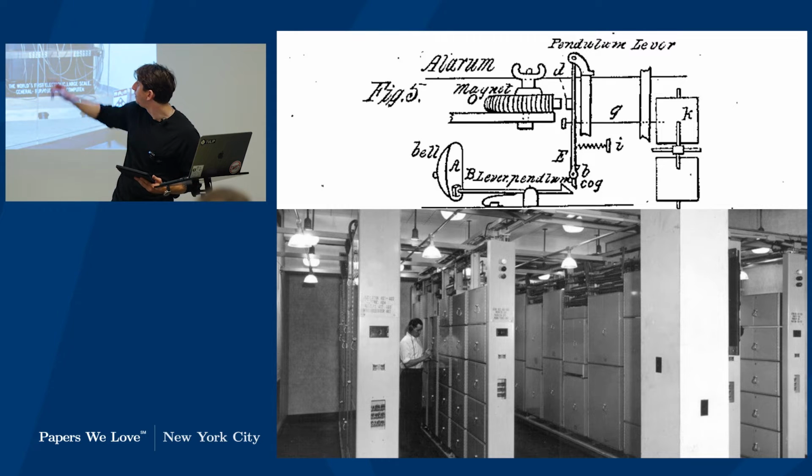You have a filament, and you have a plate, and then you have this grid in the middle. And if you run a current through the grid, you're basically able to accelerate electrons from the filament to the plate. So they act as really useful amplifiers, and this is where they were originally deployed at Bell Labs. But you can also imagine how you can use them to have these three prongs and simulate various circuits. And we also see a vacuum tube-based computer here.